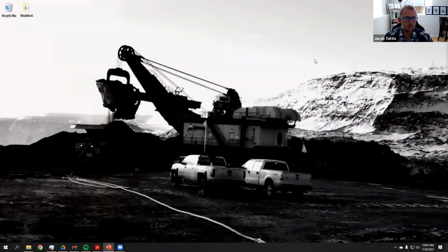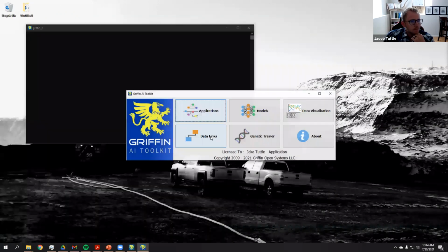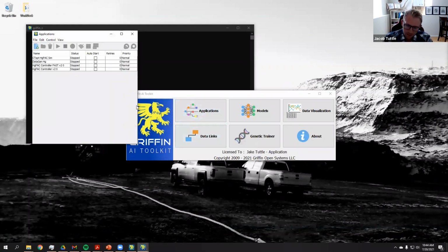So I'm going to actually break out of the slideshow and open up the application that was built on site. One of the key things that's important to this was the fact that mercury is monitored on a 30-day average. Their emission rates are a 30-day average, or opacity, 6-minute averages of their opacity reading will cause them to be in violation. And so that's one of the process characteristics that is really difficult to capture in rudimentary DCS control. But Griffin has the flexibility to work with that and to leverage those characteristics.